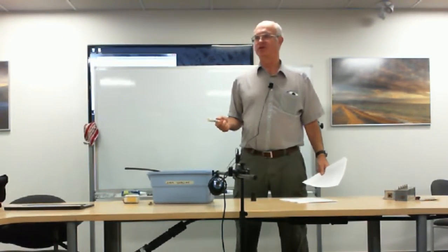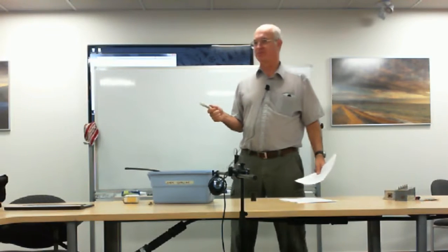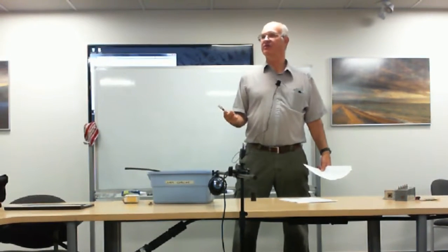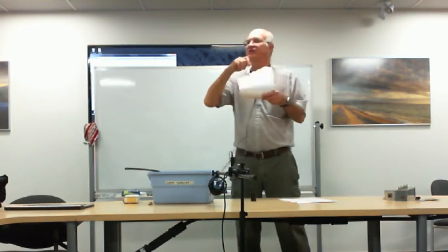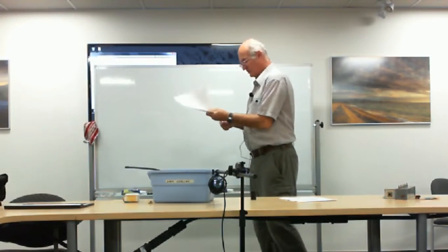Remember the golden rule that whenever you mix frequencies together, you get the sum, the difference, and the two originals. Don't forget that. That'll be on the test too. That's really important to understand mixing and everything else. Whenever you mix two frequencies together, you always get the two originals, the sum, and the difference. And from other mixes, you get all the harmonics as well. But those are the main guys.